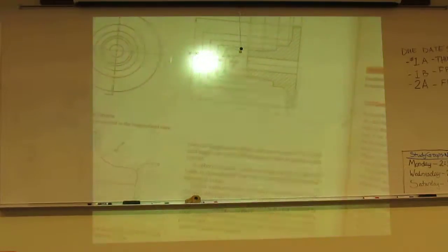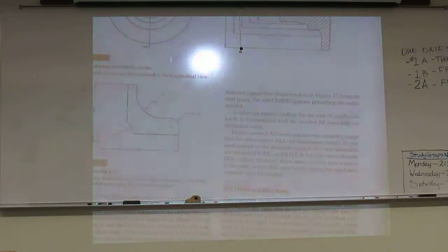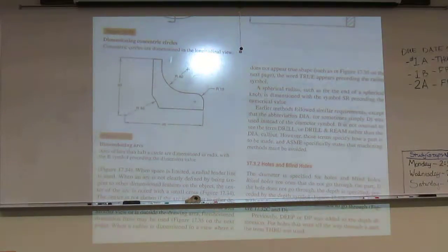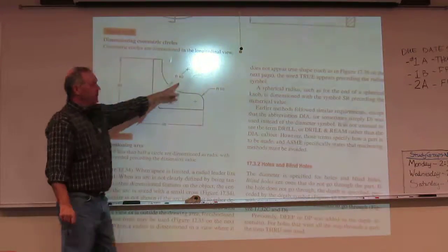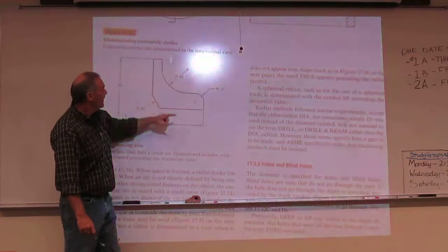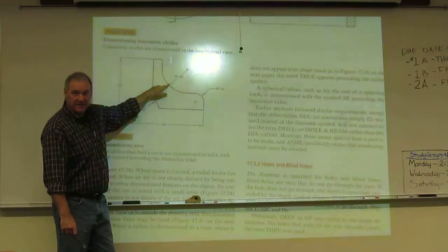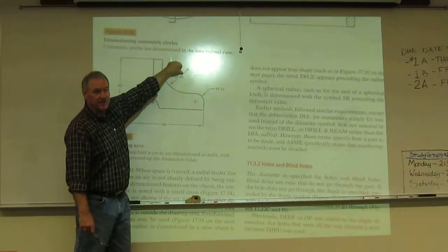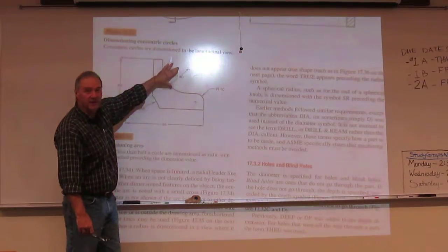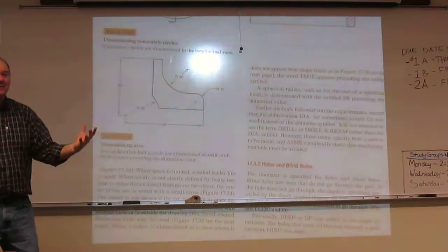Okay, I'm going to go to your text on this. I'm on 832, I believe, is the one. So when we're talking about these radii, 832. Folks, this is what your radius should be. Remember, any partial curve, anything that's not a full circle, gets a radius. What we'd really like to see is a tick mark. Our leader line points to the inside of the curve. The text is inserted inside of this, approximately in the center. That's preferred on everything. Now, we're going to get to situations where that doesn't work.